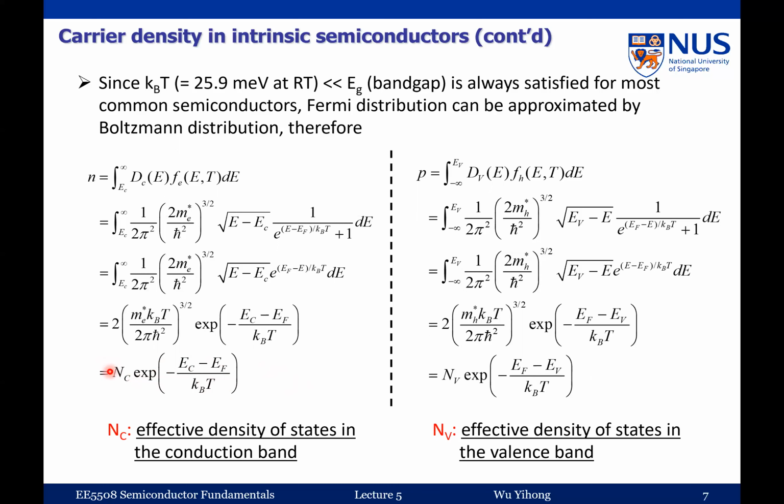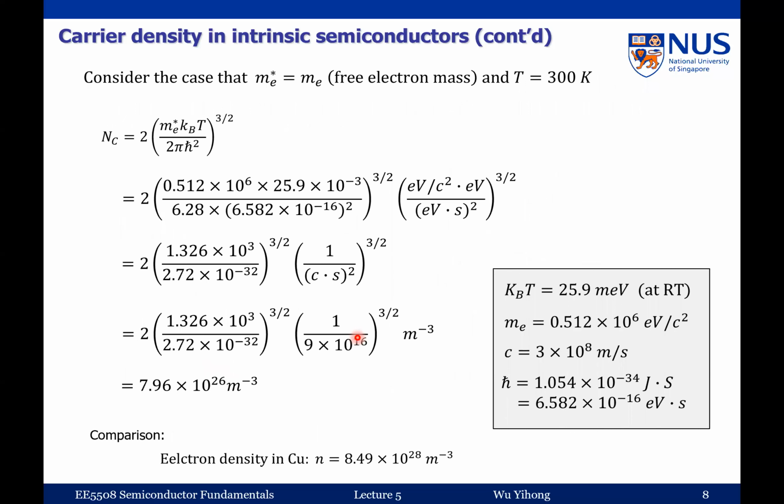And you also know that this EF is an extremely important parameter. For semiconductor statistics, the only single parameter which is important is the Fermi level. If you can control this, then you can control the carrier concentration in the semiconductor, right? Of course, in metal, you cannot do that. In metal, this EF is always fixed. So later I'll talk about this one.